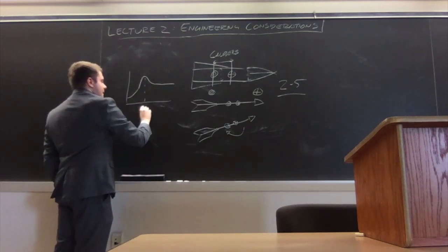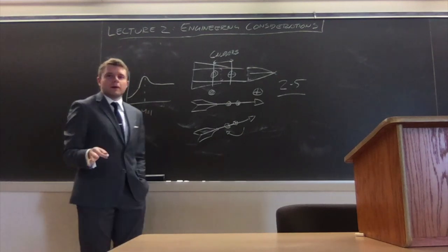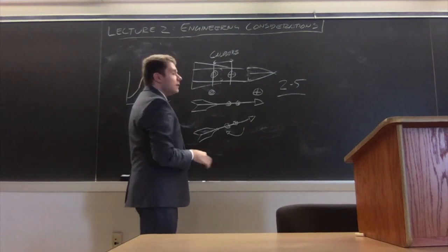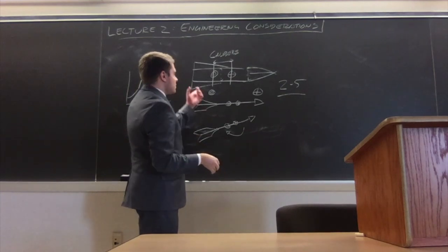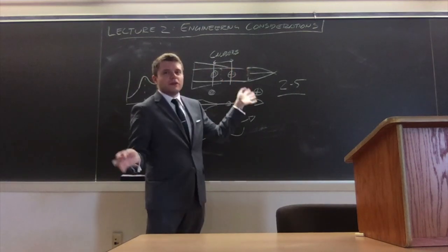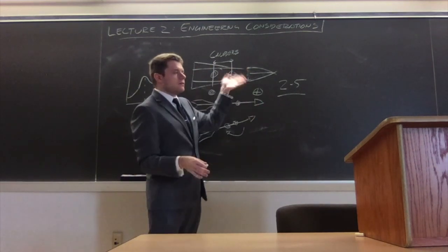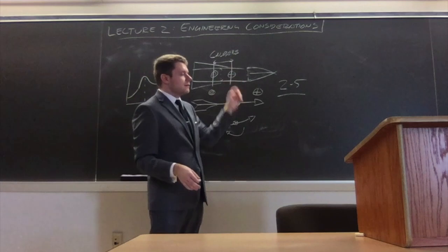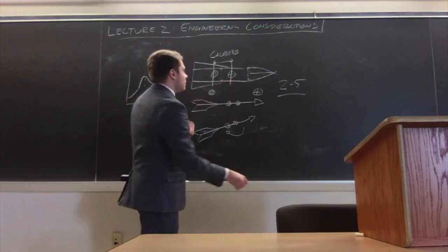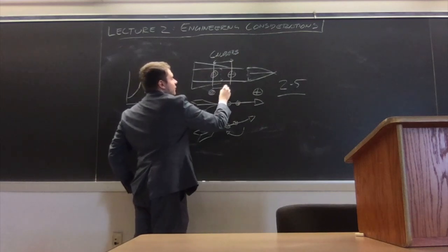In short, things behave really weird when you go transonic. Rockets are, of course, no exception. What you may have is the situation where the fins become a little bit less efficient at keeping everything stable, because the body's a cylinder. You can kind of treat its geometric center as the same as its center of pressure, more or less. The fins become less efficient at speed, so your center of pressure actually pulls forward.